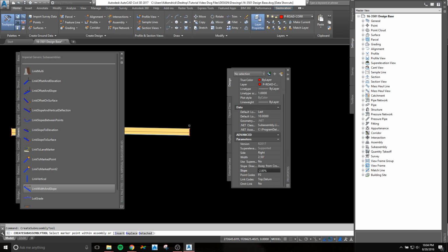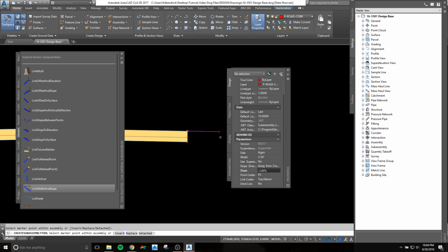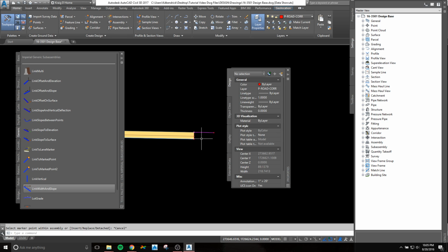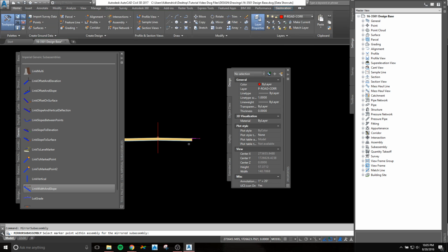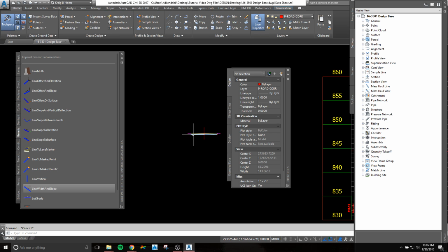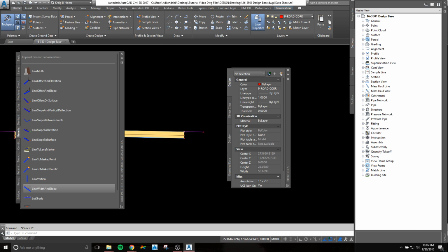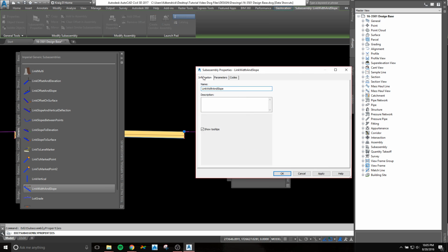So after you've set that information in, click on this connecting circle here. That gives me the offset. That's going to be the difference, like the grass strip or a median, utility median in between my sidewalk. You can also mirror that one as well. So if you right click, hit mirror, just put it on the other side, and we'll call this grass strip.